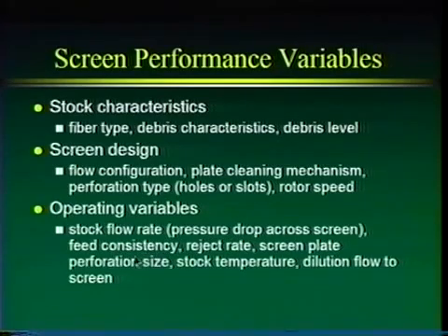What's our feed consistency? The higher the consistency, the more likely we have a higher consistency mat forming on the face of the screen, and that's going to create resistance for flow to the accepts. What's our reject rate? That's going to impact things. What's our screen plate perforation size? I would put that up under screen design. Stock temperature impacts our viscosity.